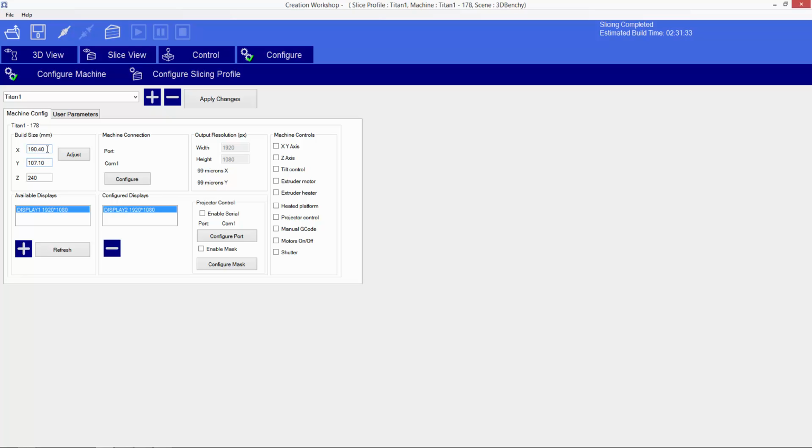as precisely as possible. And so basically, I projected this into the vat, marked the width and height, and then entered those into the build size here. I mean, I measured the build size optically. I didn't measure the build size based on a real print. And the reason why I recommend doing it this way is actually based on a series of posts on the forum by another one of our early users, T Dixon 1000, and he builds some very accurate engineering models for his engineering and machining business.